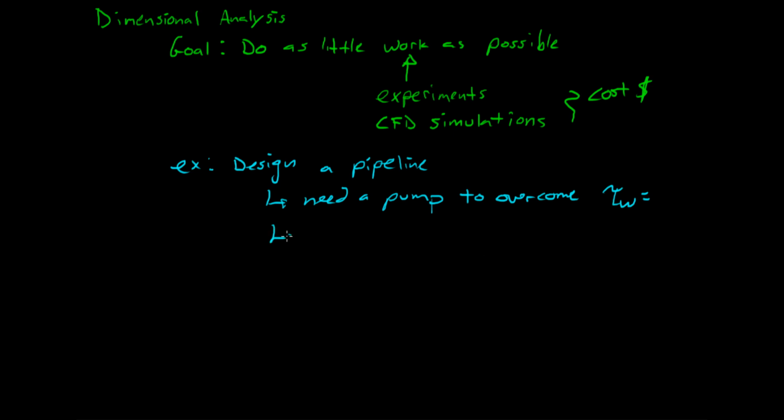Well, we know that shear stress, or the shear force, the overall force acting on the fluid, depends on, wow, I can spell today. Depends on area. Which area? Well, the outer cylinder of our pipe, right? Not the cross-section area, but the surface area. That's where the shear stress acts. And so that area looks like a function of diameter and length.